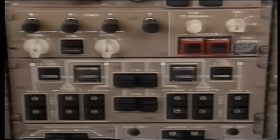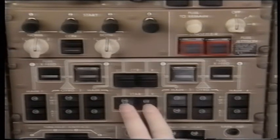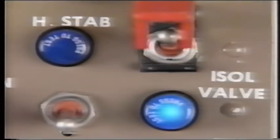Depending on the position of the tab, fuel can be directed overboard or from tank to tank when the manual shutoff valve is open. Fuel can then be pumped out of the main tanks or the center wing tank by opening the cross-feed valves and turning on the fuel boost pumps or override jettison pumps. The HST can be defueled by turning on the transfer pump switches and opening the HST isolation valves using the fueling panel switch. The boost pumps will remove most of the fuel from the tanks. To remove all of the fuel, the sump drains must be opened to remove residual fuel.